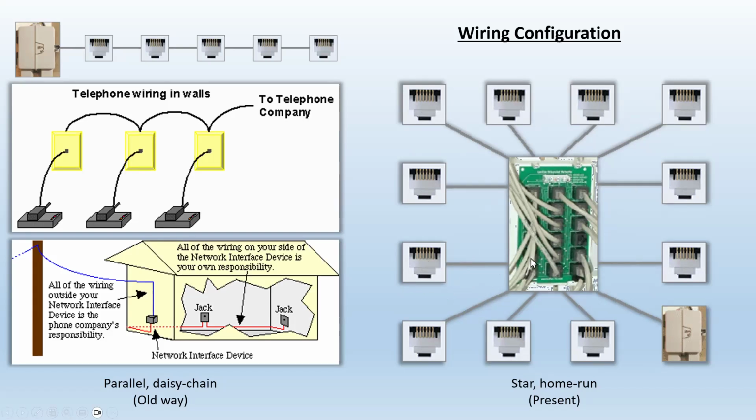So if you connect a phone signal on one end, that phone signal is going to be conveyed right to the jack where it is. So that's how we connect things now. We just connect phone jacks just as data jacks, and we run them in a star configuration, star topology, so now each jack can be used as data or phone, if you want to use it one way or the other.